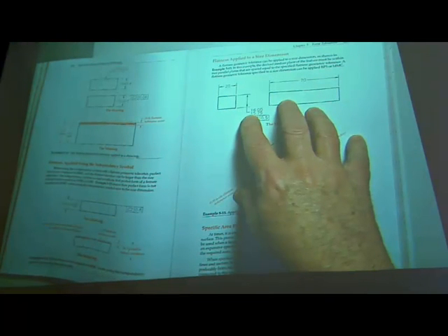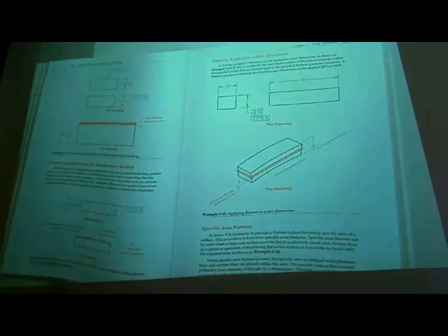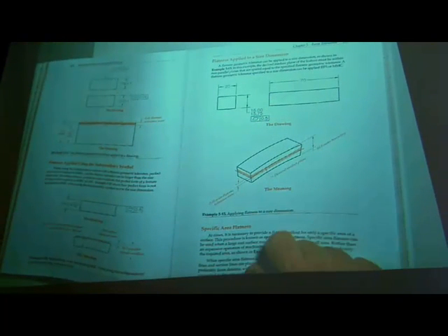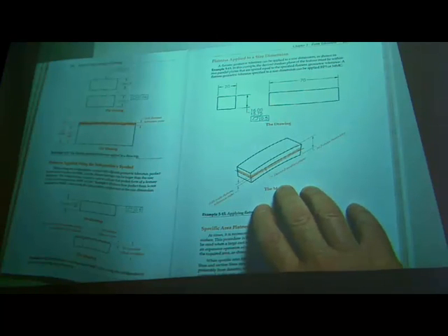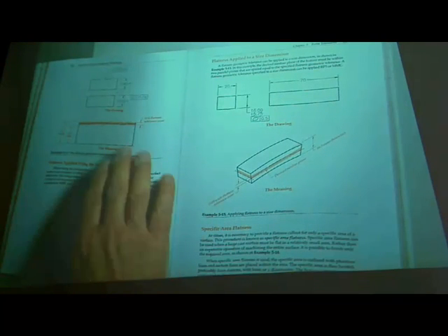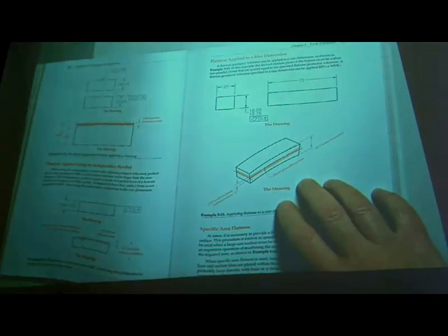It's just, this is possible. Someone may specify it this way. You're going to be using the outside shape to determine what that median plane looks like. So I would just stick with standard flatness control, myself.